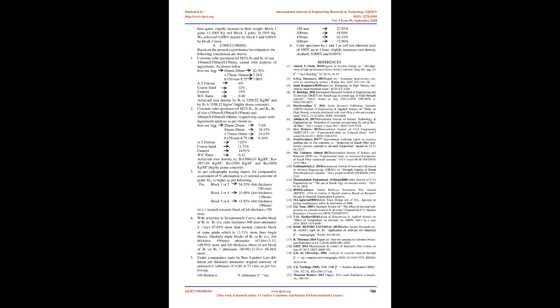Concrete shielding. It can be used to shield against both neutrons and gamma rays. It is composed of a mixture of cement 13%, water 7%, aggregates 80%. OPC is referred to as light and has a density of about 2.2 to 2.4 g/cm3. Heavy concretes have densities ranging from about 3 to 6 g/cm3. Ferrophosphorus or limonite aggregate mixtures have been used because of their greater densities and higher water content. The barium sulfate aggregate, baryte, is also used to form heavy concrete.